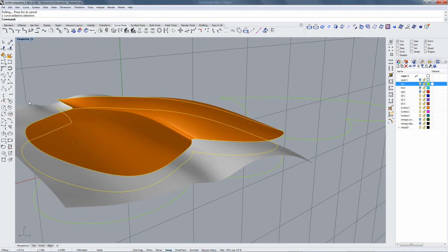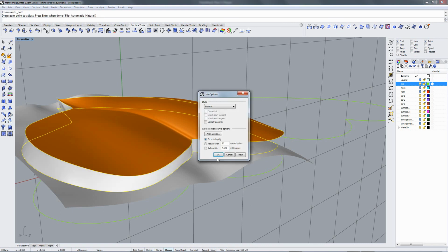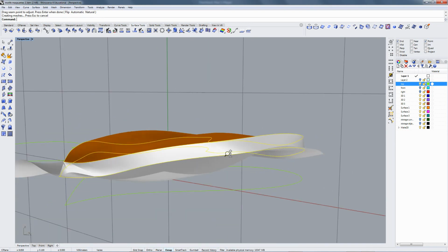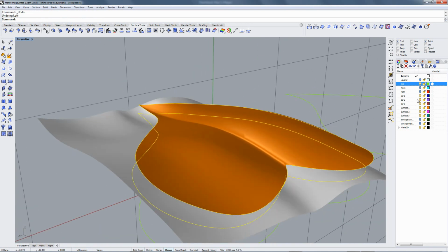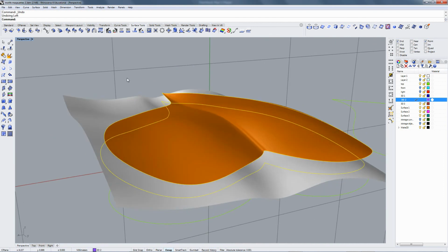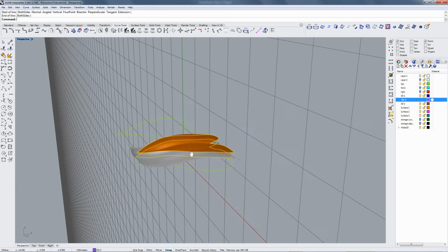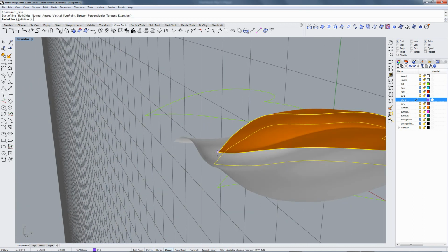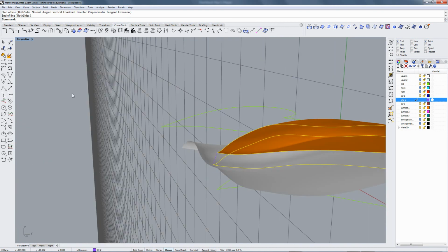And then I can do a lofted surface here. Chances are I'm going to need to do a bi-rail sweep, but we'll try a loft. See how I'm getting some very strange shearing? I don't want that. So I'll give it two cross sections to manage. End to end, end to end, and now do bi-rail sweep.